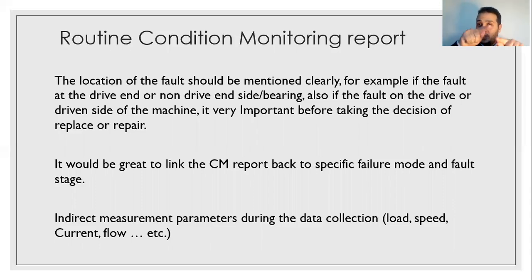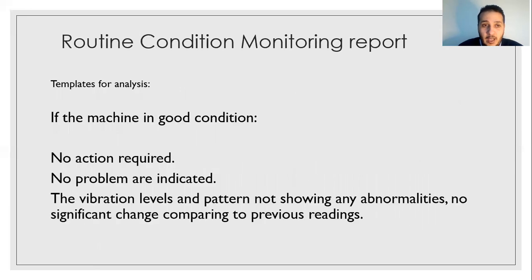So when you have your trend with vibration levels, and this trend is linked with the load or with the valve angle, you can see that when the valve angle is at this position, the vibration is at this level. When you change the valve angle, the vibration drops. So it's more linked to the process, not to a mechanical or electrical fault inside the machine.